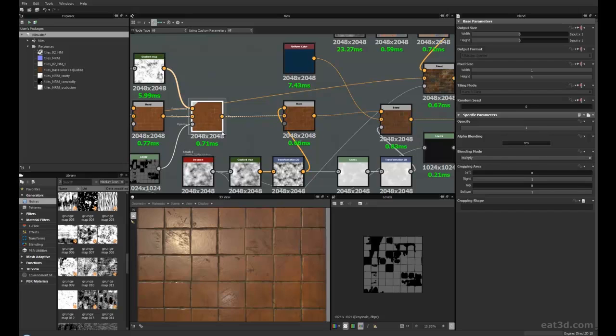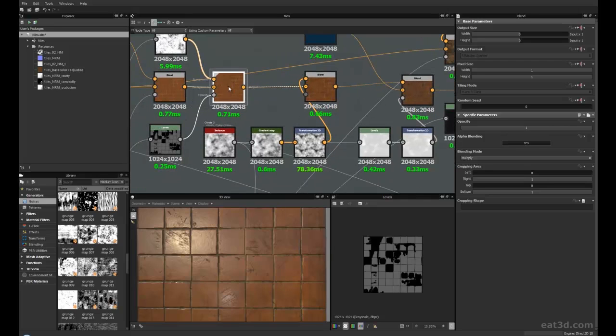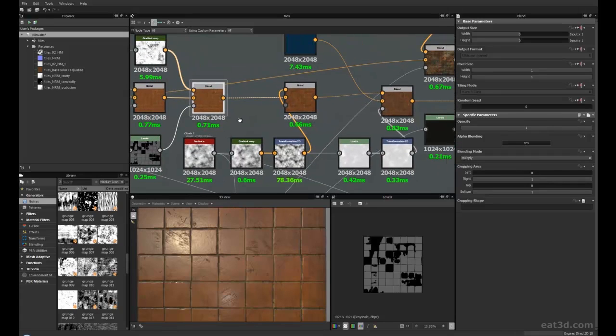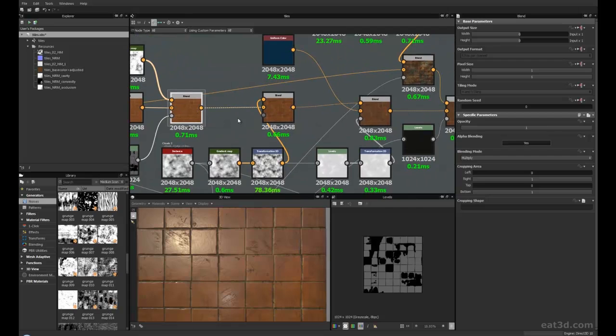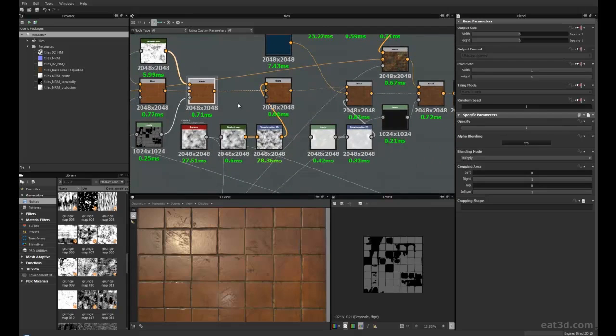With multiply, it's going to keep the blacks and get rid of the whites. So because that blend is on multiply, it's keeping the black scratches and getting rid of the white. And then we're using the mask to drive where we actually want it, and a levels command to tell it exactly how much of the black needs to show through. I hope that makes sense. Okay, let's move on to the next part.